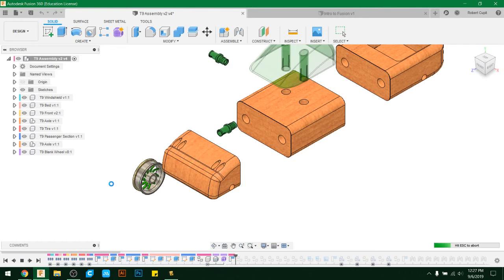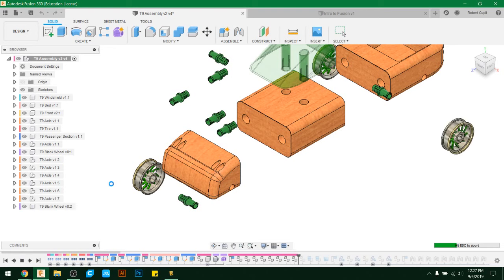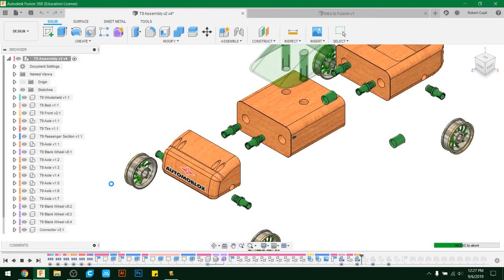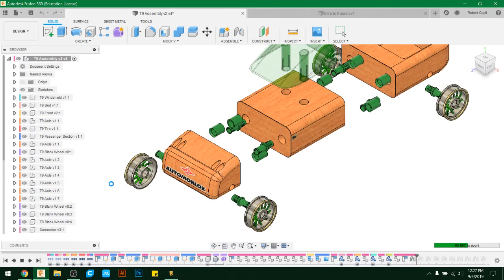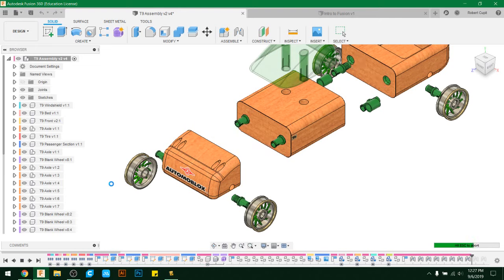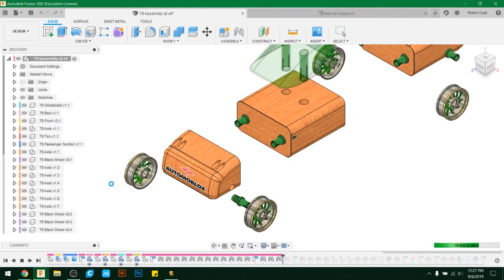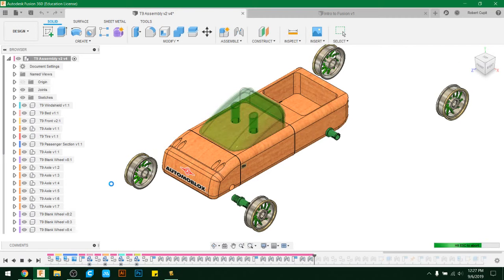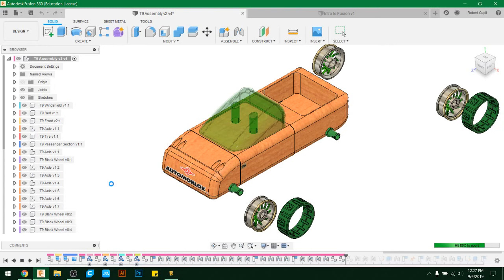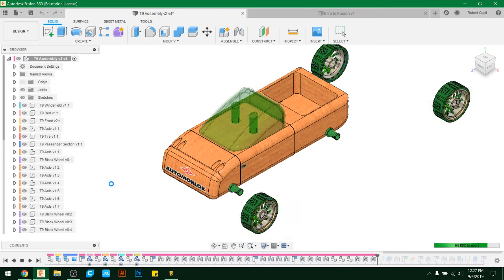Let's say I screw something up. I'm at the very end and I notice my tire was just a little too small or a little too big. You can then move that little black line that you see moving, as a play button right now at the bottom of the screen, to wherever you want and then edit that feature. And then go all the way back to the end and it'll fix it for everything. It's kind of like reverse in time. You can mess with things and kind of go back in time to see things. Questions or concerns on that?